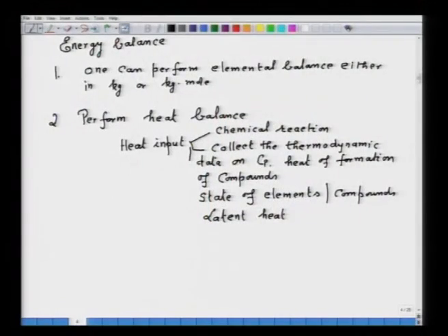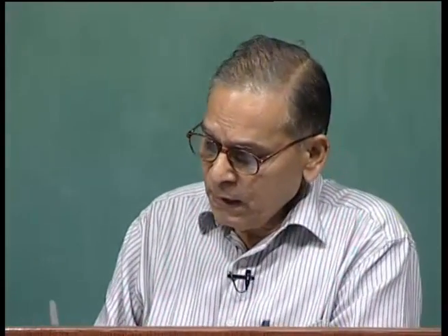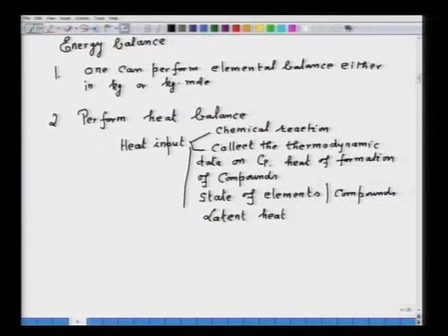Then you should also know the melting point. Then the important thing over here is to know the latent heats. Why I have written this is simply because many times I have seen in performing heat balance, we might forget latent heat, but well there is no reason for forgetting. So, latent heat, now this latent heat could be for transformation either in the solid state or in the liquid transformation, say from solid to liquid and liquid to gas. At each stage you have to see what is the latent heat. Also heat input could be say a sort of combustion energy.